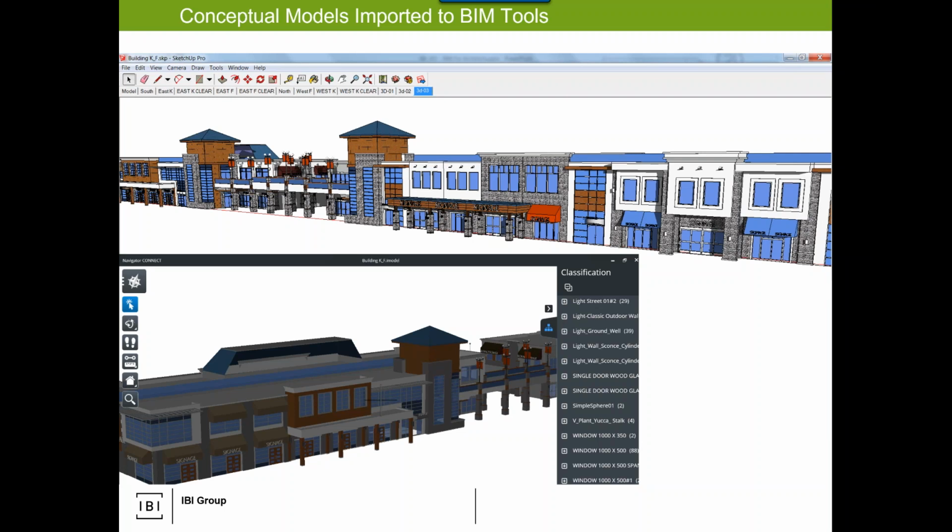So when you're defining a technical solution, and I hear this a lot, Revit is not fluid enough to allow me to be an architect. I need to use Rhino, I need to use SketchUp, I need to use whatever. As a BIM coordinator, we can't go in there and say, sorry, you can't do your concept design. We have to go in there with a solution to say, all right, you're doing concept in tool X. We're going to be doing full BIM authorship in tool Y. I need to define a workflow to get from X to Y. And that workflow could be just testing, it could be a simple export import, or it could be an actual robust workflow in order to facilitate the needs of the project. And that's a workflow owned and governed by the BIM coordinator.